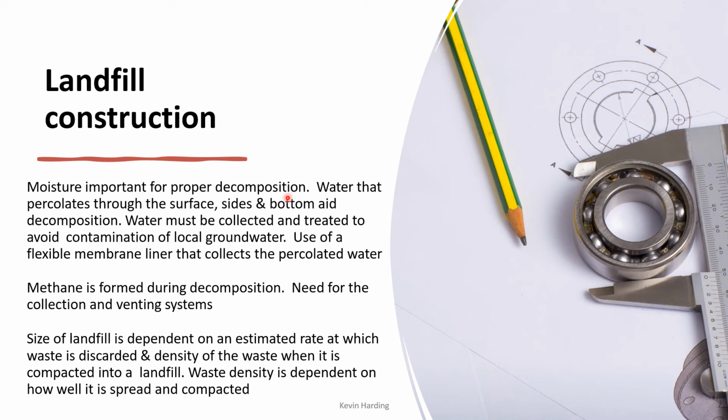So water is the lifeblood for microorganisms. Microorganisms are often in liquid systems. They need water to grow and breathe. And if we are going to have microbial decomposition or biological breakdown of certain materials, these microorganisms need water. So we need that water in there. However, that water that percolates through the surface and aids the decomposition is going to end up in the local groundwater if we don't collect and treat it somehow to avoid that contamination. To do that, we often use a flexible membrane liner that collects the percolated water. And I'll get to that in another slide in a bit.